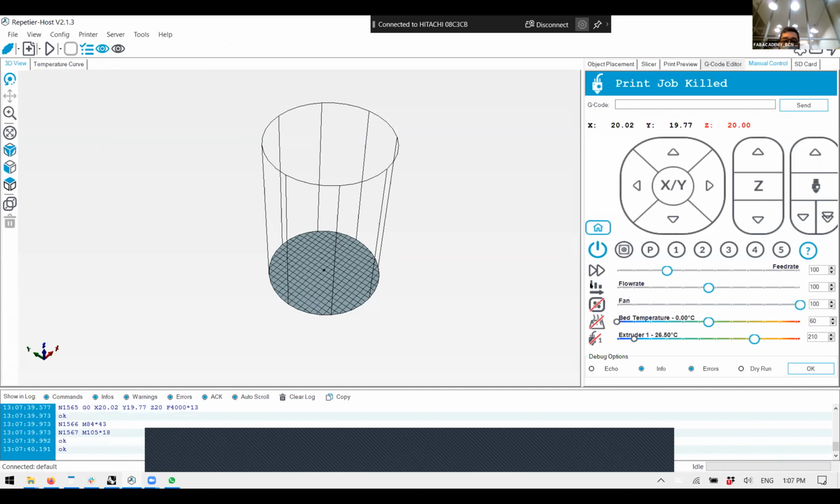So let's kill this. Pressure. Yeah, right. Another bad point of the system is, I always state the bad points of the system, but actually most of the time it's the one that I use because it's clean. The pressure when the cartridge is full is different than when the cartridge is empty, because there is less friction on the material. So when the cartridge is getting empty, you need to reduce the pressure a little bit. With this system, you need to adjust the pressure up and down a little all the time, depending on the machine.